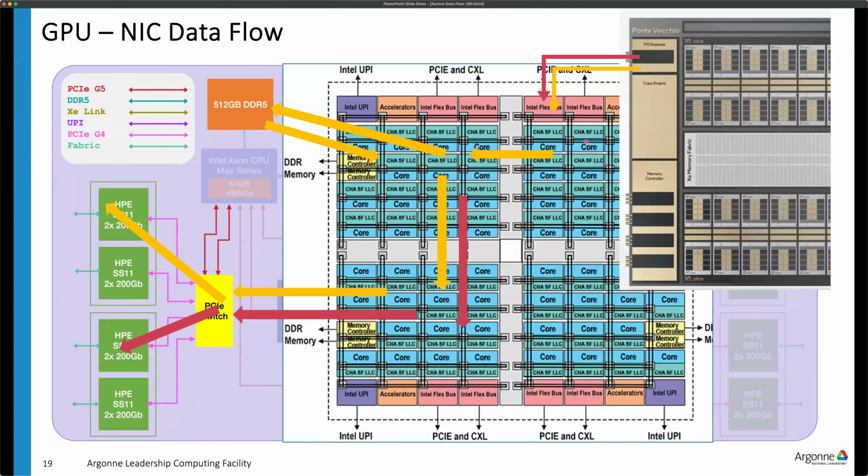The advantage of directly going out through the core bus without going to a piece of memory on the CPU side is you get better latencies, but your throughput or the bandwidth is lower. Whereas if you were to basically move it to the host memory and then push it through the PCI switch and the network card, you get a higher bandwidth, but you pay the additional latency cost of moving it to the host memory.